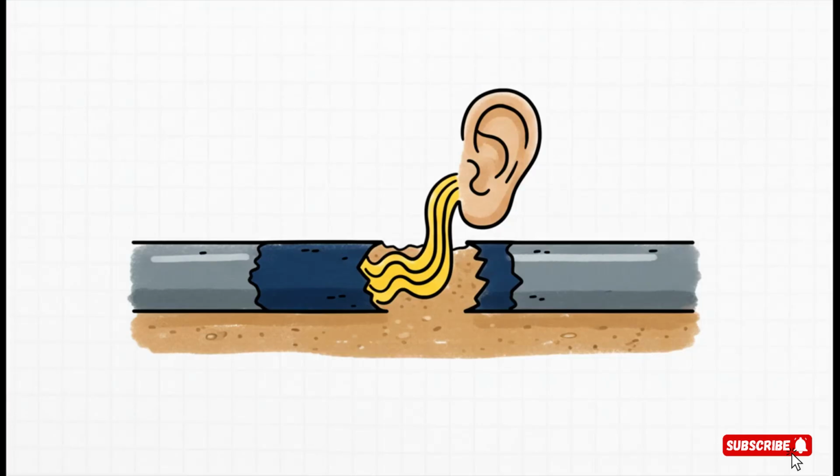Probably the easiest way to get your head around ACCA, which stands for Alternating Current Attenuation, is to use an analogy. Just imagine that the protective current we're putting on the pipe is like a sound traveling through it. If the coating is in great shape, it's like a perfectly insulated tube. It keeps all the sound in. But if there are faults or defects, the sound starts to leak out. ACCA is basically the microphone we use to listen for where that sound is escaping the most.